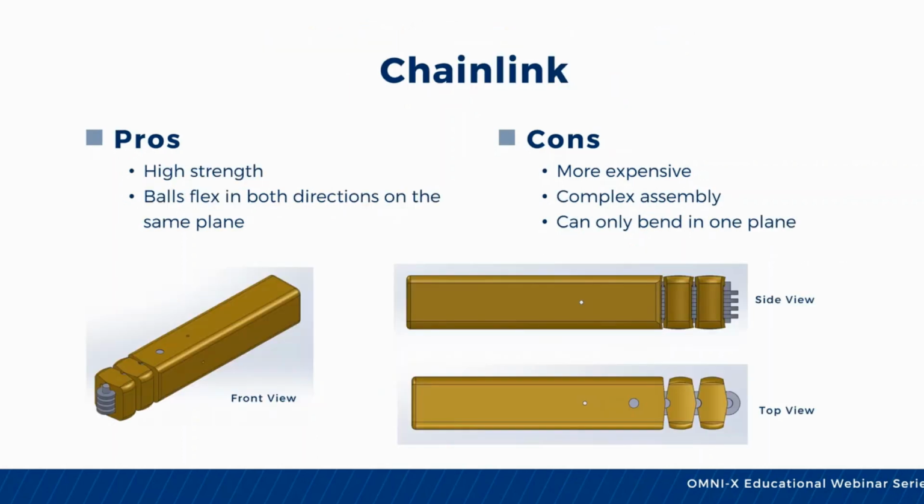Another alternative to traditional mandrels would be chain link mandrels. These are typically used for square, rectangular, and shaped mandrels due to strength advantages. Chain links can be used for round mandrels for specific applications where more link strength is required, but cost significantly more than traditional links, and require the machine to be modified to ensure that the mandrel stays aligned to the bend plane and does not rotate like a normal mandrel. These links are stronger than normal round links due to the single plane of bend. You can reassemble these links, but it is much more complicated than normal links.